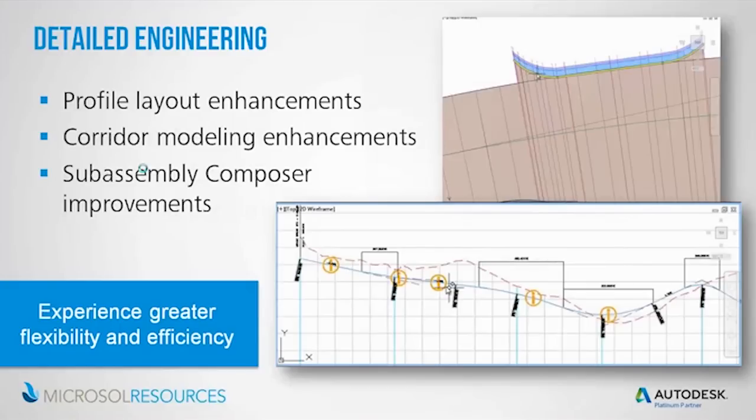So the first section is called detailed engineering, and you'll see that there are several improvements for the way profiles are laid out. You can get notifications now if a profile changes in regards to where a horizontal alignment has been modified. You'll see that there are new corridor modeling enhancements. This is probably easier to view than explain, but any of you who have done some extensive corridor modeling know that if you have an offset assembly or you're using an offset parameter to target, let's say, a width, the ability to micromanage some of the features within that region, whether it's adding more frequent sections or replacing a particular subassembly within the corridor and having it rebuild automatically with the exact targets, hasn't been available. So those are some of the things that I'll show you.